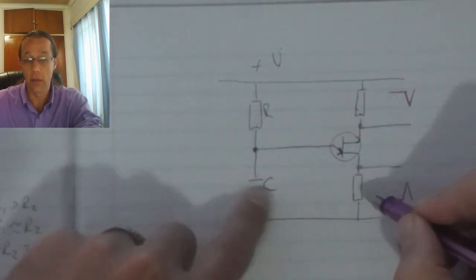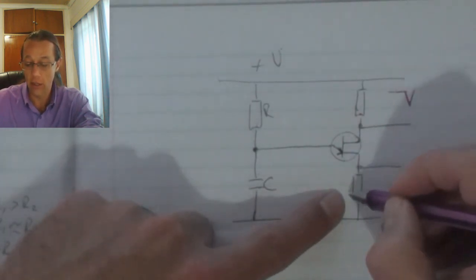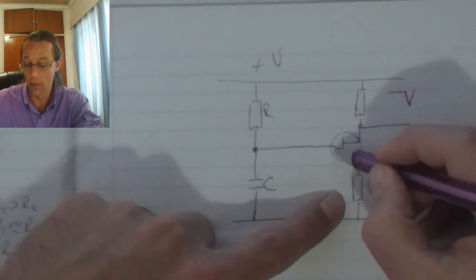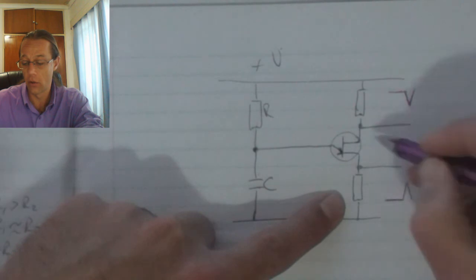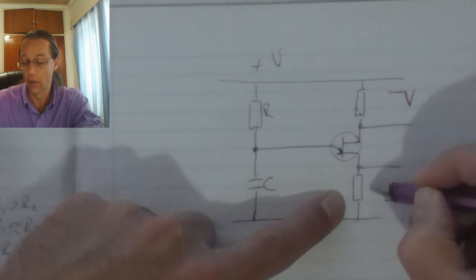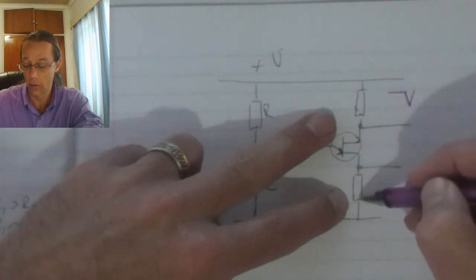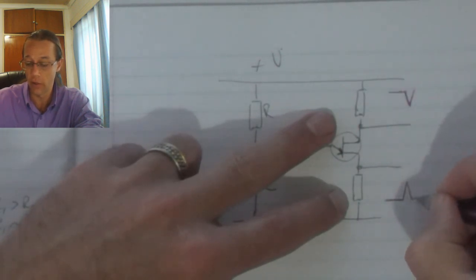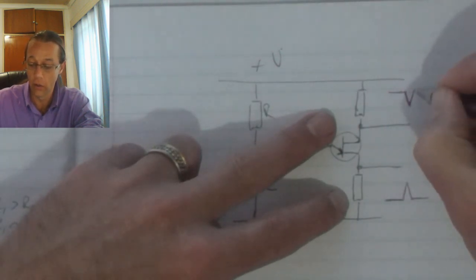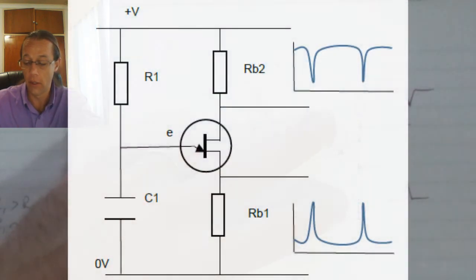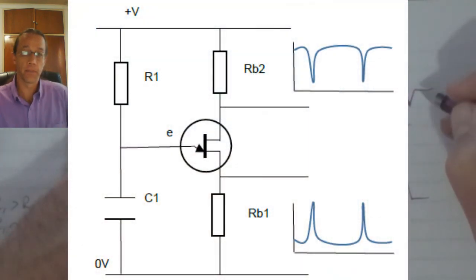Once this capacitor has discharged, this base emitter junction will cause a depletion region to be reformed. That will in turn return the current flow through this half of the circuit back to normal, and as a result the voltage on these two will be normal again.